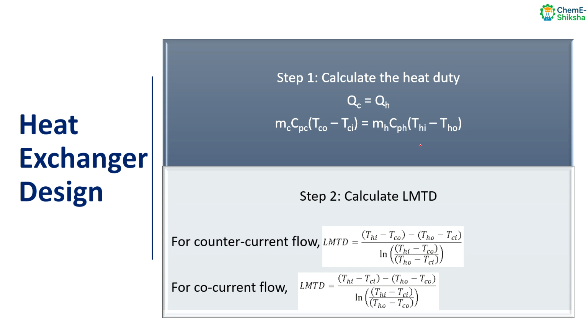So first of all, when we want to design a heat exchanger, we first need to know the heat duty of the heat exchanger. So we know the heat exchanged by the cold fluid, that is QC, will be exactly equal to the heat exchanged by the hot fluid. That means the amount of heat that will be exchanged by the hot fluid will be gained by the cold fluid.